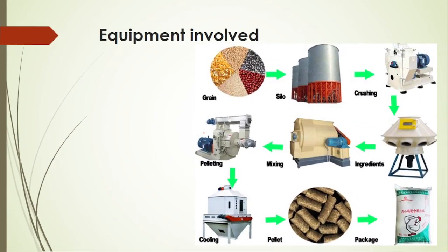Now we learn about various equipment which is used in the processing of feed. So here, the batch mixer. When we use the batch mixer, generally all ingredients are loaded into the mixer and mixed until a homogeneous material is produced and discharged from the mixer in a single lot, and the output of a batch mixer is measured in kilograms per batch.